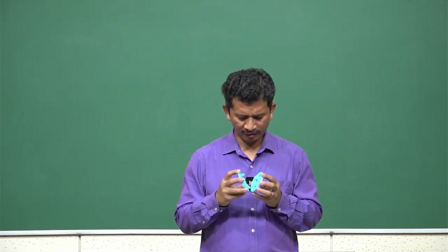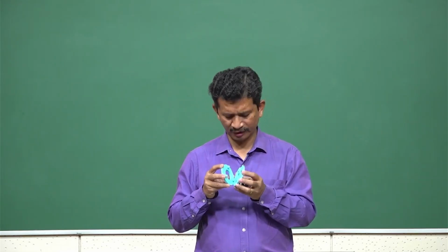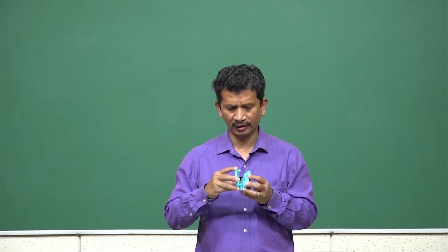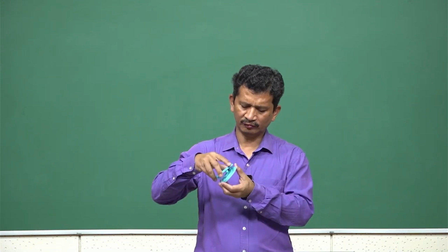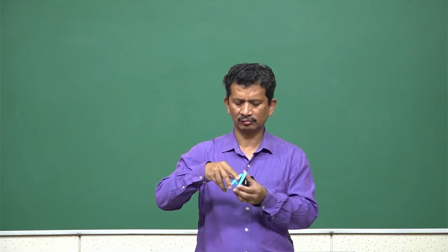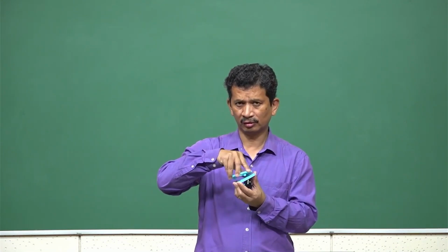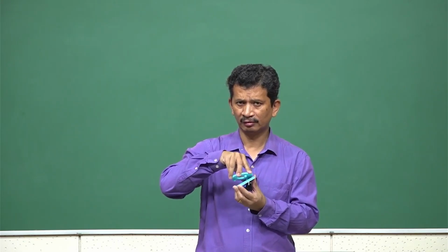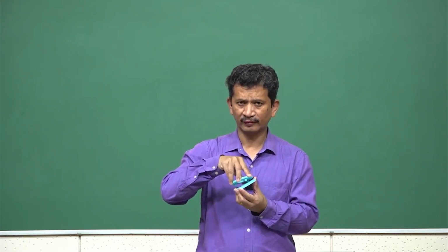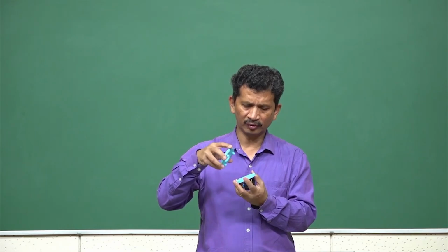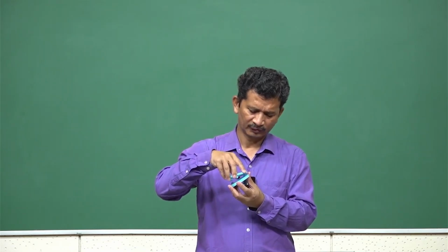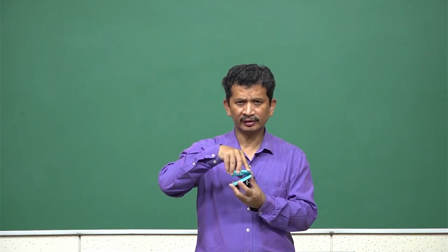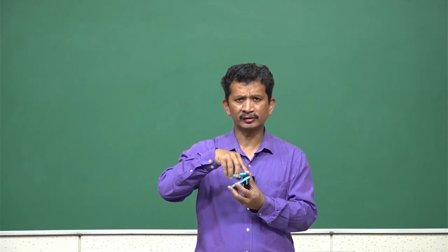When this ball comes in contact with the V groove, we have 3 contacts. The moment we do this, we lock the position. Although the top plate can rotate along different axes, that particular ball is located by the trihedral hole, because it has 3 contacts.